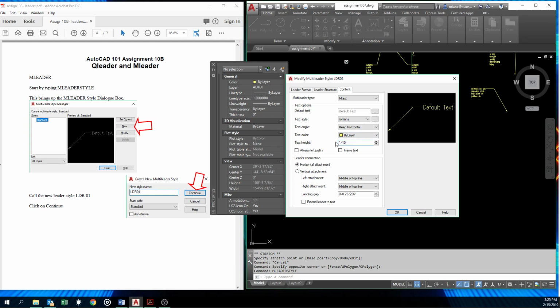So there are things that are changing drafting standards. This 1/10 of an inch high text is a good example of that. Back in the old hand drafting days, or if you have a hand drafting person in your office, they're going to tell you 1/8 of an inch is standard. Well, 1/8 of an inch was standard because that was easy on your ruler. The architectural scale had that laid out. It was very easy to make 1/8 of an inch high text. The idea about 1/8 of an inch high text was that was what was legible. If you made a half size set, that 1/16 of an inch high text is about as good as you're going to be able to read. Anything smaller than that just got too small, especially in handwriting.